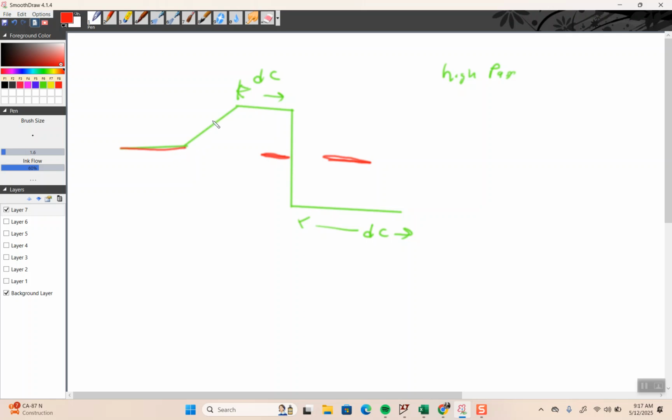But here, it's actually detecting a slope, so it will pass that slope after some time, but it's taking the derivative. So it might do something like this. It takes a while to adjust, and then it's flat. Now it's DC, so it's going to take time to go back to 0. Now here is a negative edge, so I'm going to detect the negative part, and then it's going to go back to 0. And depending on tau, it'll either take longer or shorter.